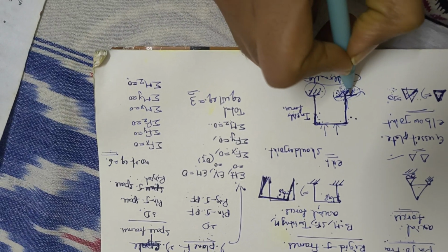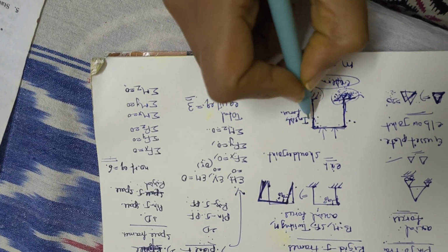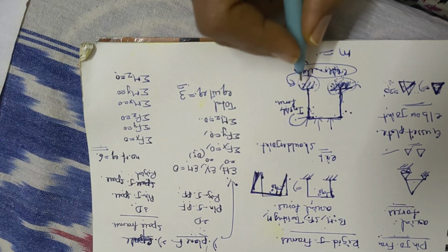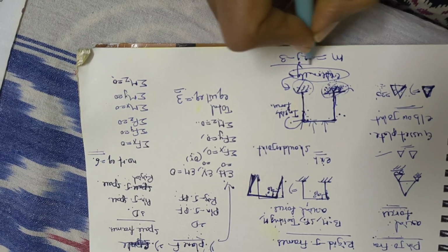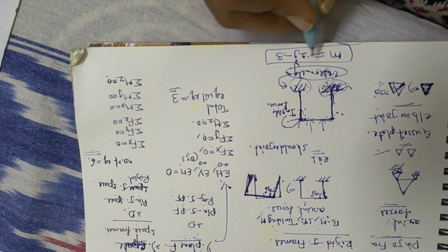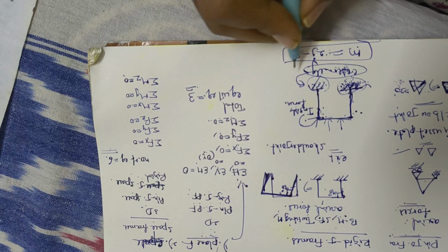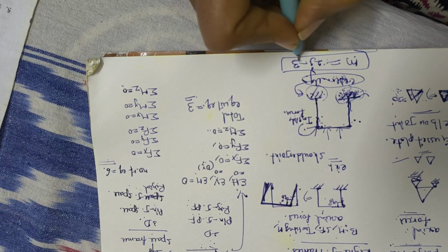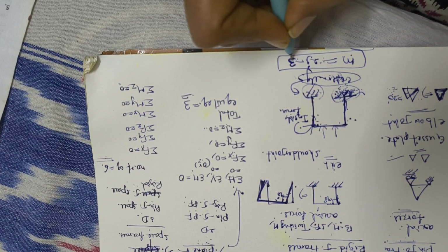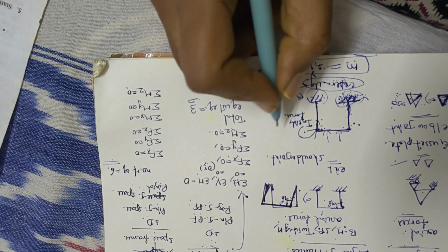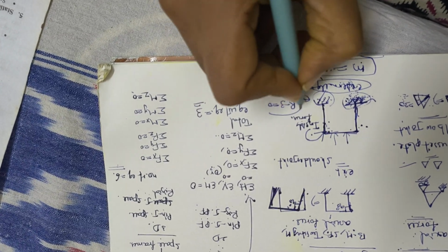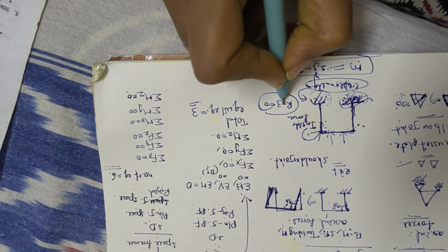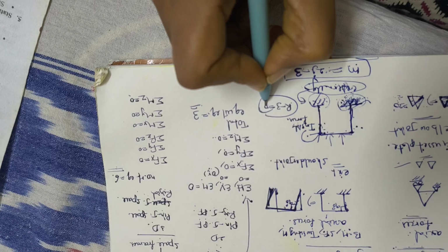External stability depends on supports, and internal stability depends on members and also the joints. We have one formula, m equals 2j minus 3. The number of members equals 2 times the number of joints minus the equilibrium equations. Here, the equilibrium equations are 3, as I am writing for a 2D frame. Or otherwise you can check r minus 3 equals 0, I mean the number of reaction forces developed in the given structure minus equilibrium equations equals 0.